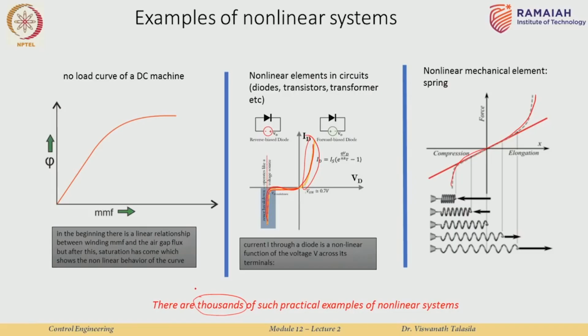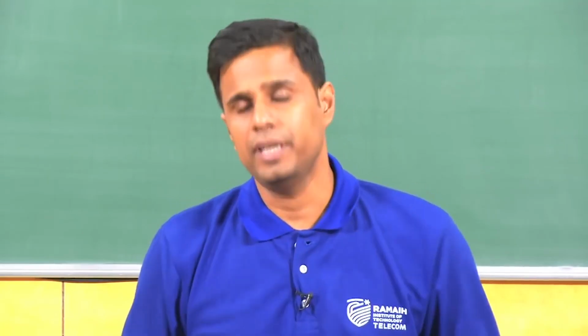For example, I can have a spring which is like this, which looks almost linear everywhere, and my range of operation of this particular spring, depending on the application I am looking at, may be only in this range, and I do not need to worry about what happens over here or over here, because my operation happens in this particular range. In this case, it is enough for me to just use a linear model, and I do not need to worry about the nonlinear effects, and this is what happens in practical engineering. As far as possible, we try to use systems in their linear operating range.